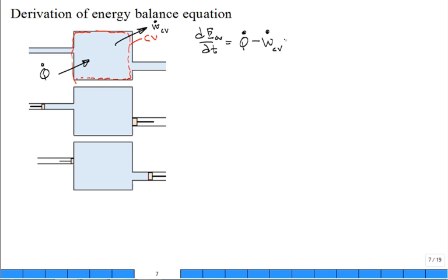All right. We're going to have the mass flow rate coming in. It brings in its internal energy. It brings in its PV. That's the magic. That's a flow work term. It brings in its 1/2 V squared. What's 1/2 V squared? Specific kinetic energy. And it brings in its gz. What's gz? Specific gravitational potential energy, or just specific potential energy. And those are all evaluated on the inlet, and I didn't leave enough room.